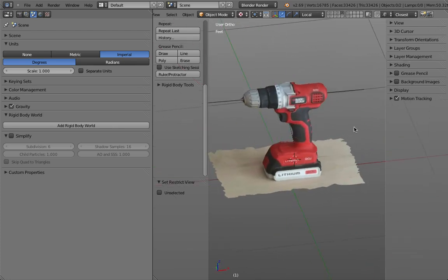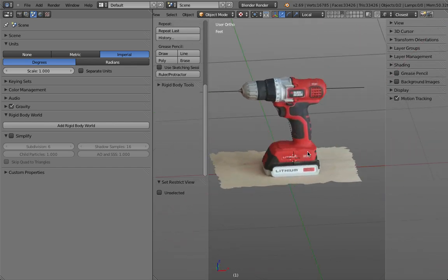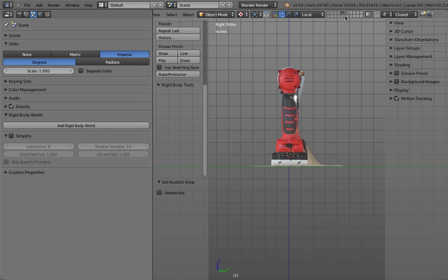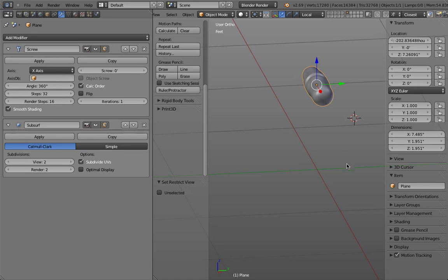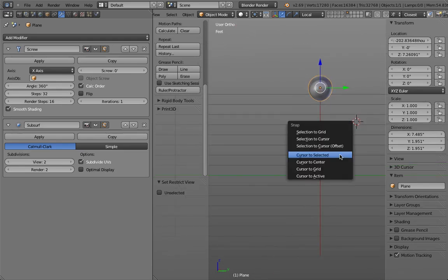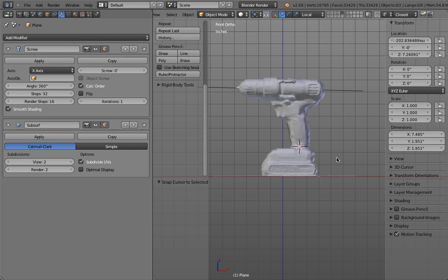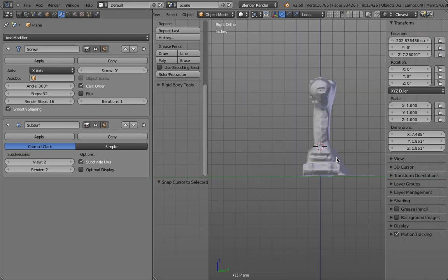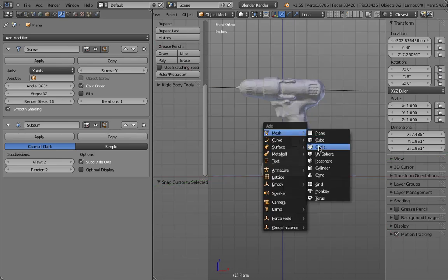And there are two ways how we can start: with a cube, and then we have to subdivide the cube, or we just start right away with a ring. And just to make sure, for example, my 3D cursor is misplaced, so I select a reference object, Shift S, cursor to selected, and then maybe from the side now I can place my cursor to here, because you see, based on the view, you can only move your cursor in certain positions. So right now Z and X, but not along the Y-axis.